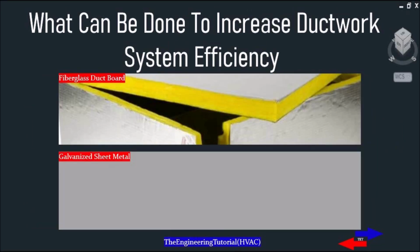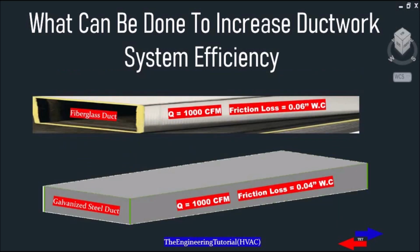So the first thing we need to take into consideration is the material which is used for the ducts, and the roughness of the material does cause friction, which is the loss of pressure that occurs in the duct due to the effect of the airflow dragging near the surface of the duct, which can cause resistance to the motion of airflow.